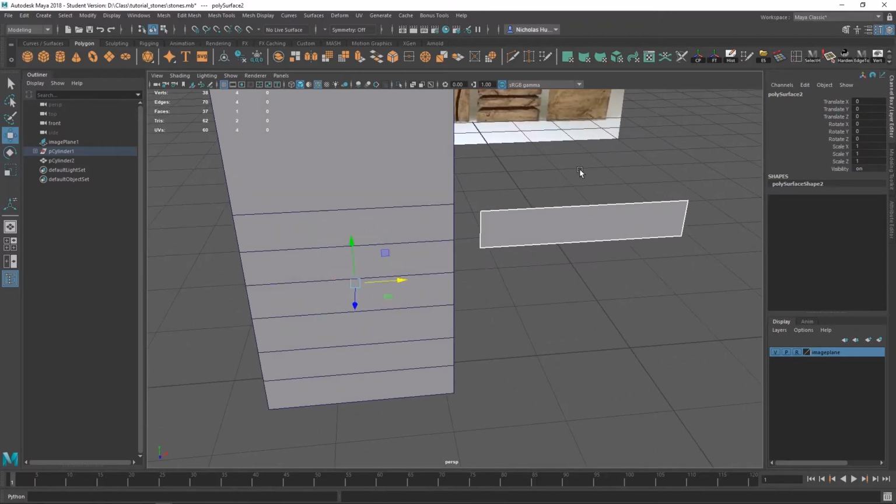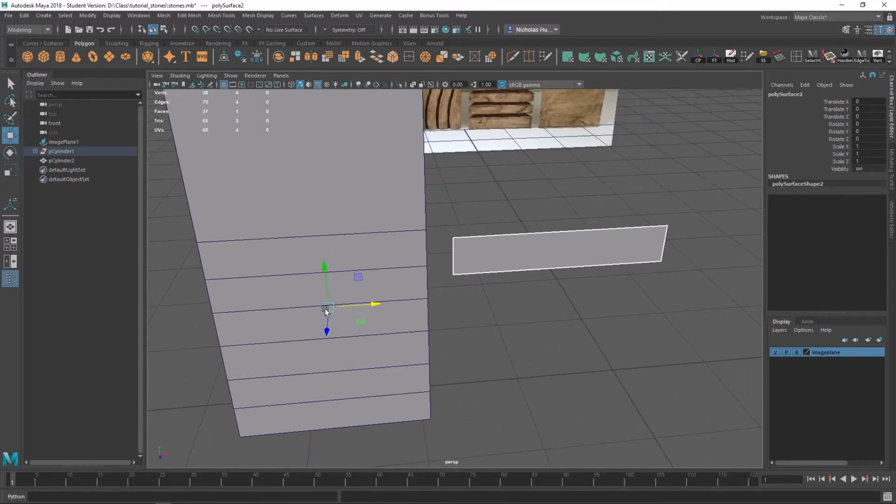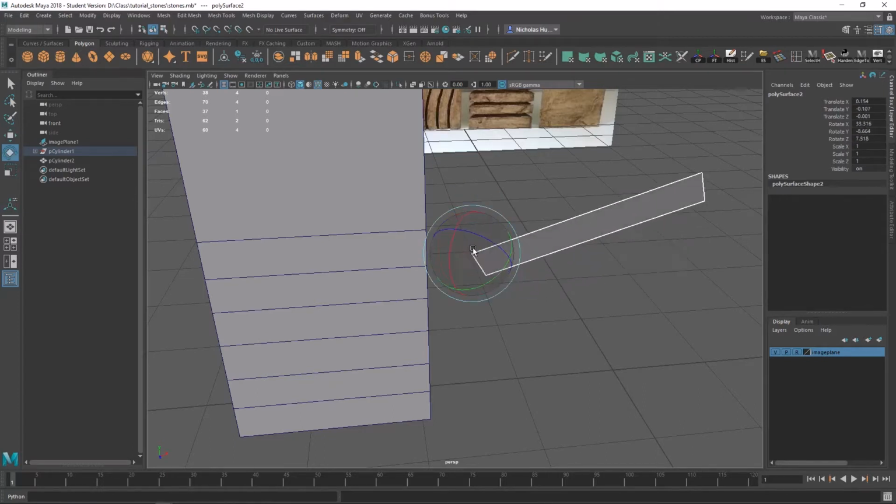I'm going to tap W real quick, and then D as in dog, and you'll notice this change. So D, and now it wants to know where I want to put the gizmo. I'm going to reorient this gizmo. So I'm going to hold down V as in Victor and the middle mouse button, and I'm going to hover over this vertice right here, and it should snap. If you hover over any other vertices, it'll snap there, but we want it to snap right here. Then I'm going to release the middle mouse button and release V. Then to say OK, this is where I want it, I'm going to tap W one more time, and then it's there. Now we can move it from there, rotate it from there, etc.